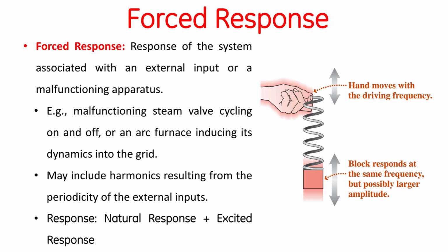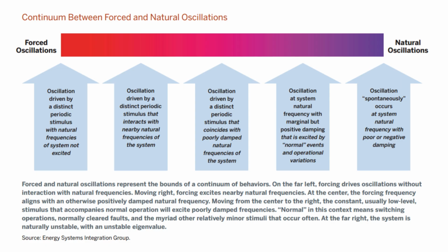Or, increasingly, you might see issues with inverter-based resources, solar farms, wind farms, battery storage. If their control systems aren't interacting correctly with the existing grid impedance, they can inadvertently inject oscillations. So the forcing function is this external rhythmic disturbance.